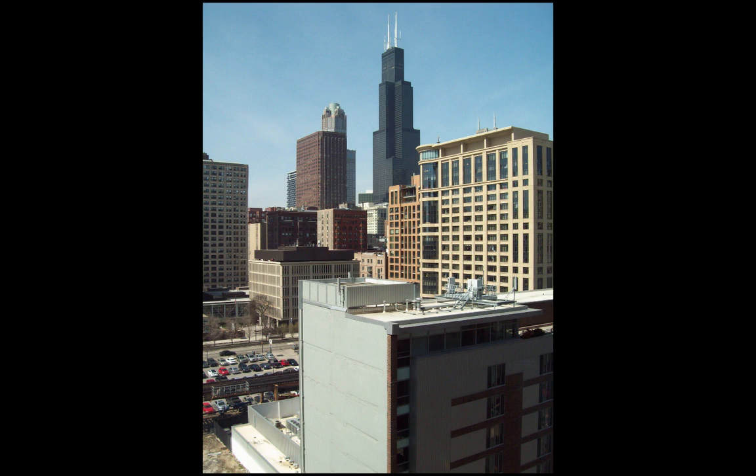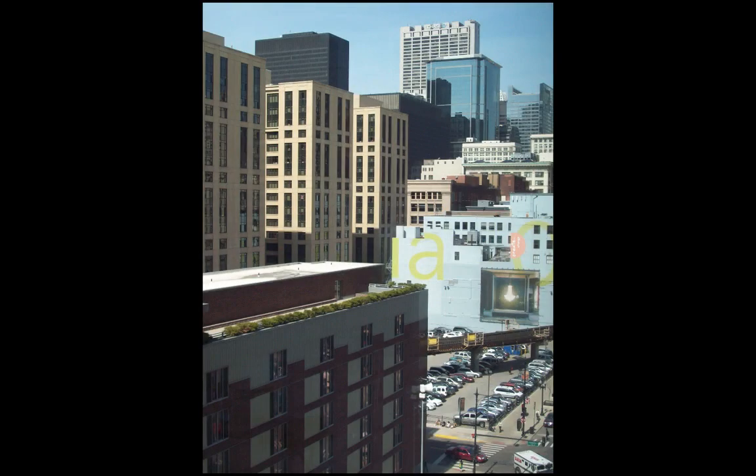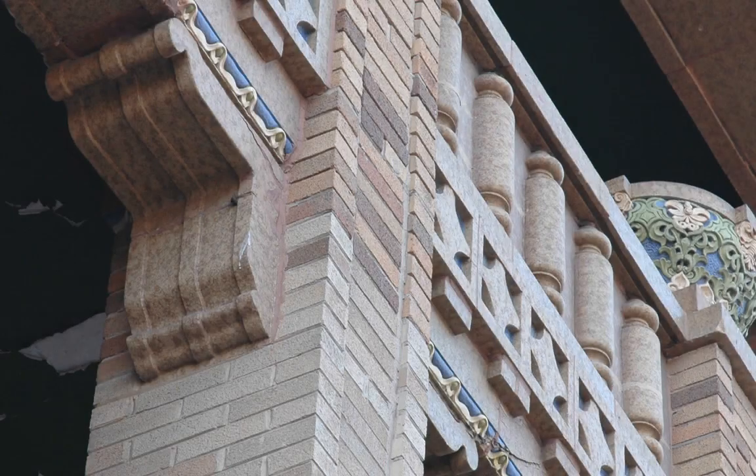This would be a three-point perspective because the Sears Tower in the back is converging to a vanishing point above. This one, where most of the buildings are centered on the line of sight, everything is two-point perspective converging on a left and right vanishing point. If you're looking up at a building, you have a three-point perspective where the parallel lines that are in the z-axis converge upward. The parallel lines on the x and y-axis converge left and right.